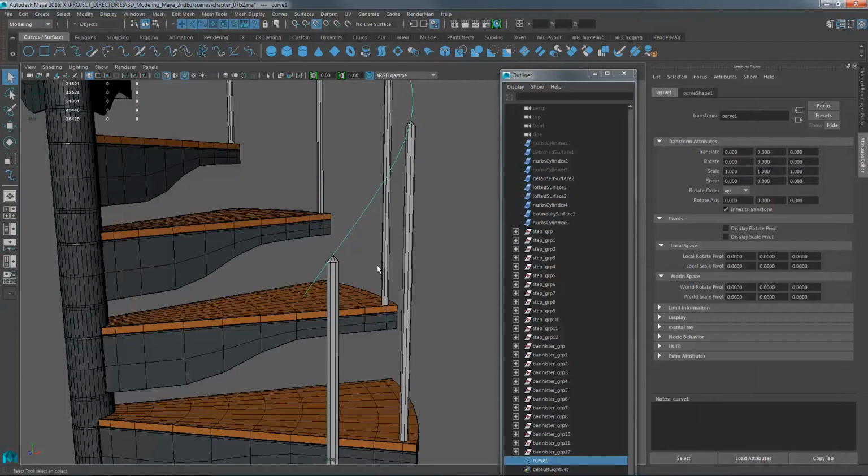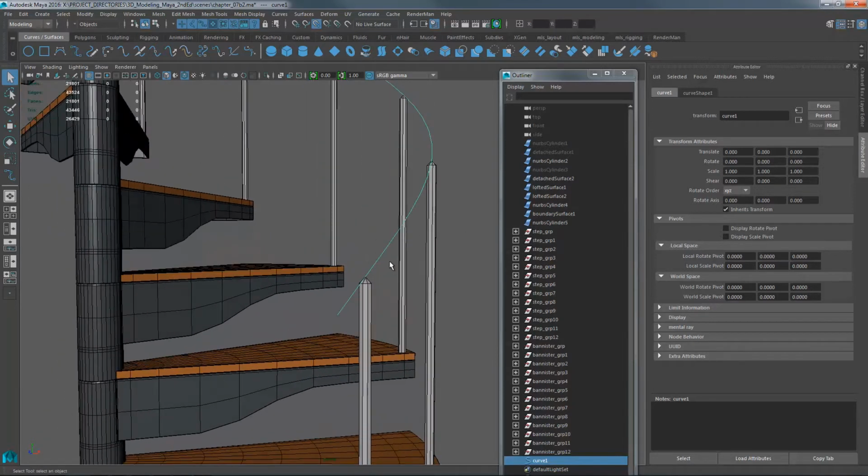Awesome drawing, right? So we can't just put a square curve along this path. We saw that earlier. At least I think we saw that earlier. Believe me, if I use a square profile and extrude it along this path, it will twist all the way up. So it doesn't work very well. What works better is a loft.